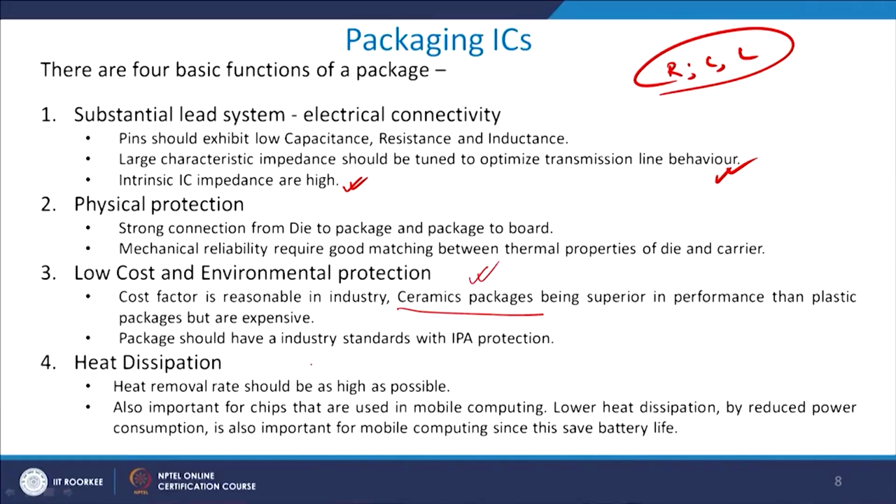So, typically what people do over the years is, if you want a package design, you first look at the package, look at the number of pins and IO pins, and then decide how to change your design so that it fits the package, right. At the last stage you cannot do it. Therefore, it is always advisable to look at the package first, and it should have industry standards as I discussed with you.